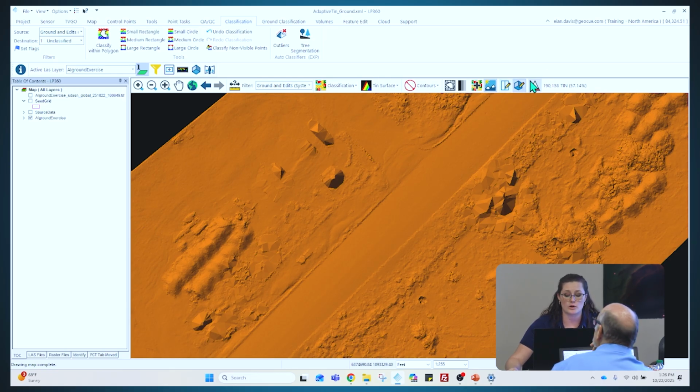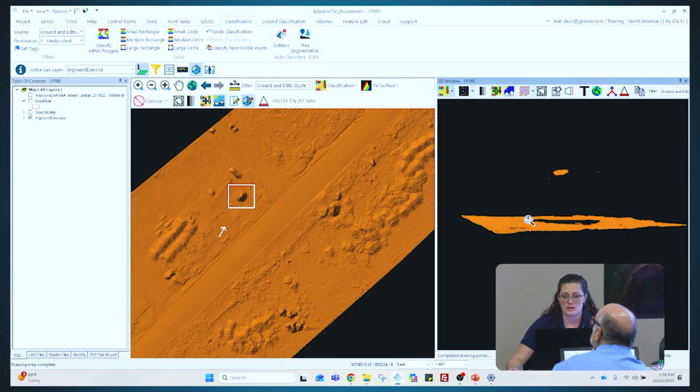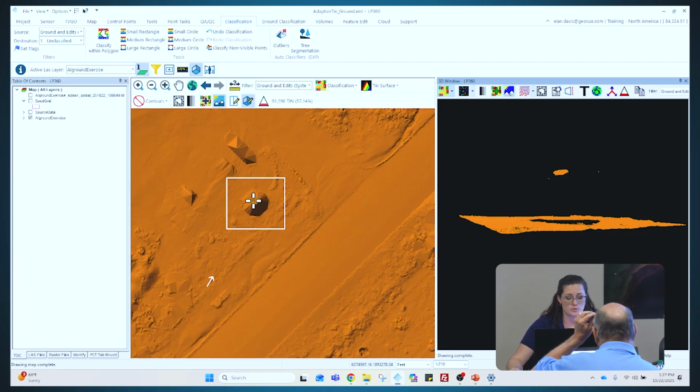Once again, a very quick way to visualize those is in the 3D viewer. I will typically draw it right here, and you can see we did get points on top of a roof or some other vertical object that is now causing this peak of sorts. These are really easy to remove from your ground surface and very easy to detect in the map view, and can be removed with simple paintbrushes.